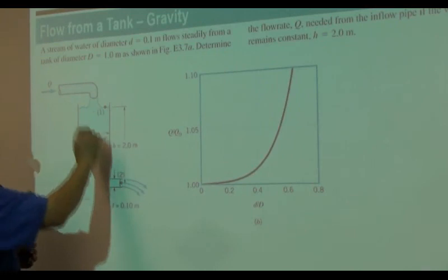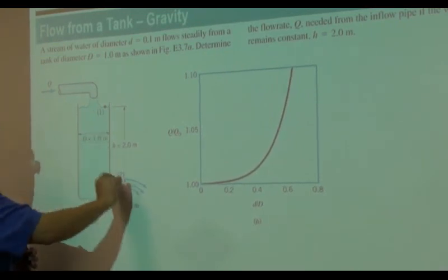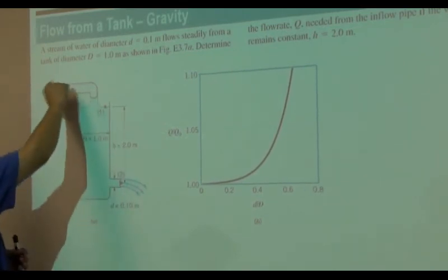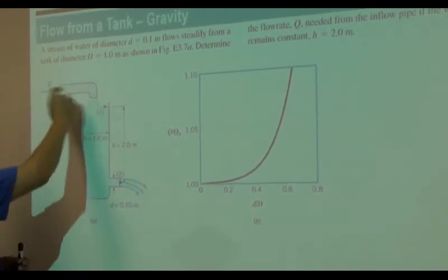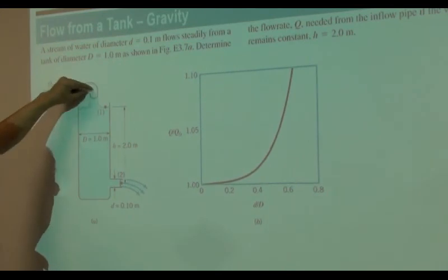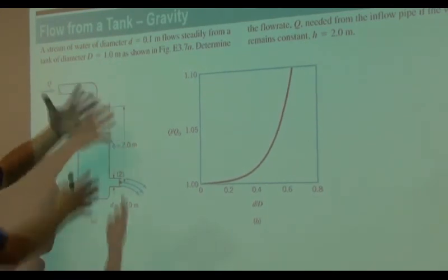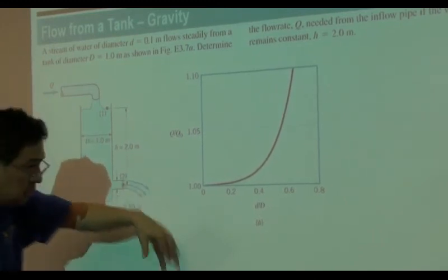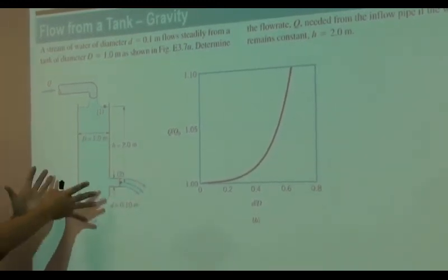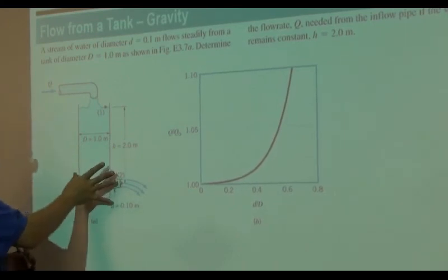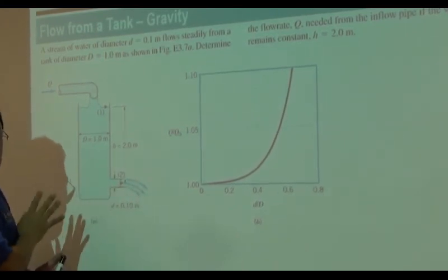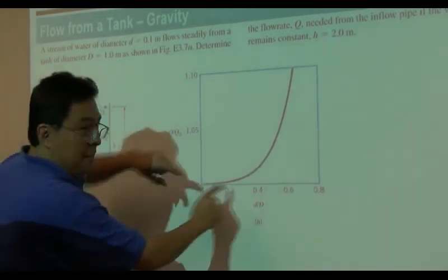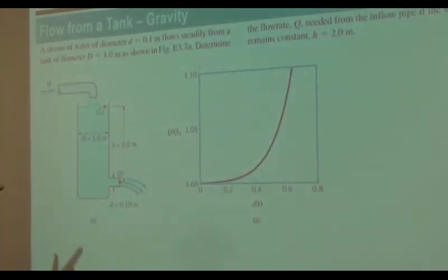But as long as you're talking about 1 meter diameter and 0.1 meter, only a small tiny amount of water is taken out, so you only need to add a small tiny amount of water. If so, once the water hits the surface, it just loses the velocity, stagnates a little bit, and then slowly picks up and flows out. That is the behavior of a large tank. So this tank can act like a large tank. It depends on the ratio. Okay? That's what you see here.